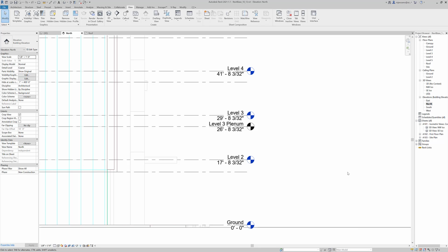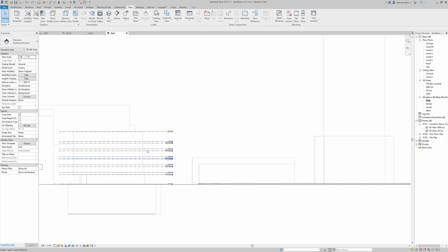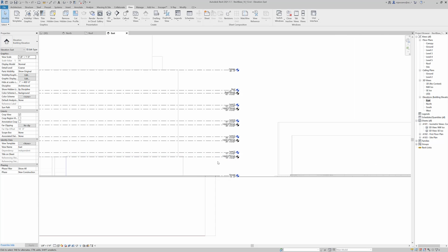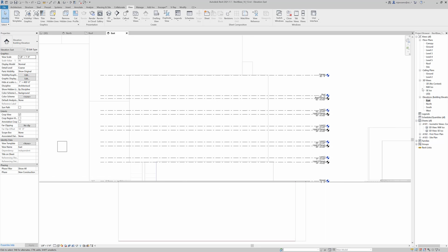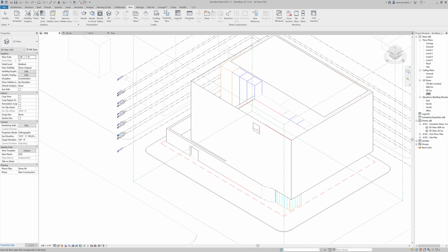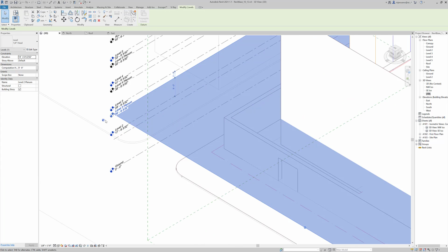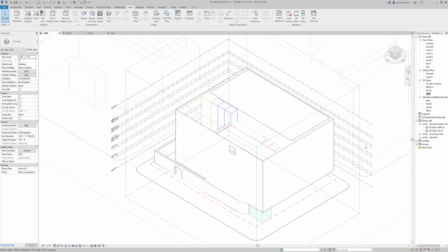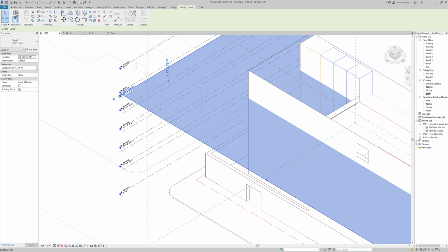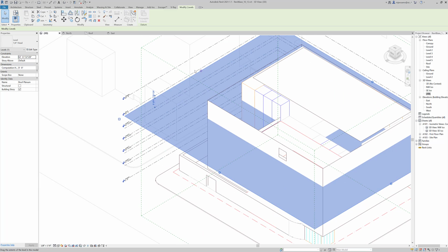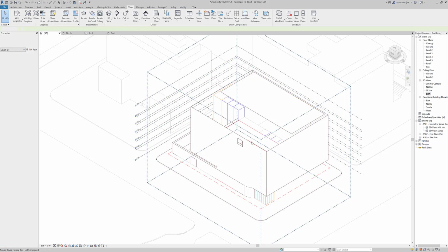Okay, I lied, that was not the last thing. The last thing is I just want to mention that your levels are not necessarily going to be in the same place for every view. So let's go ahead and go to an east elevation here. I tried to create the first level so that whenever you copy that one up, then it sort of populates to a nice area in the drawing. But you can see here that we still have to go through and uncheck these to turn them off. But most of your views should be basically created for you. But if you need to extend them or something, just know that if you do it in one, it might not populate necessarily in the other, so you just have to pay attention to that.